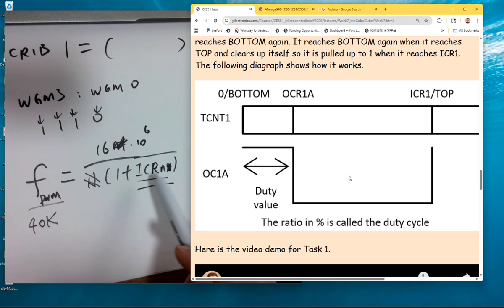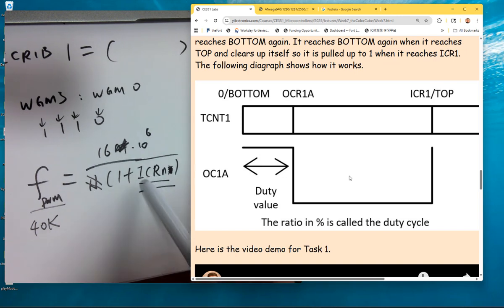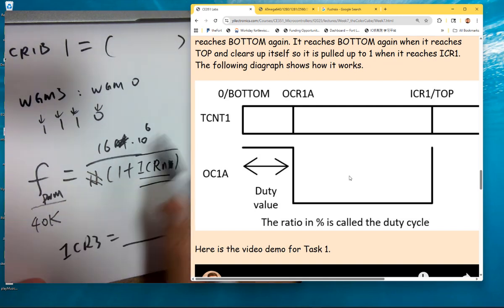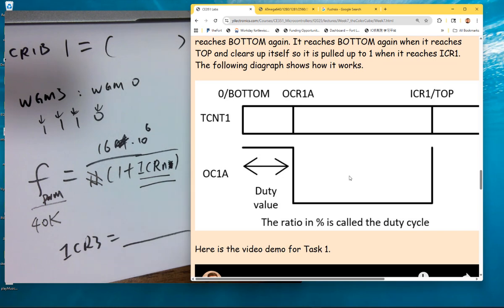So that's the register you want to assign to. And if you're looking at the problem, it's module 3, it's timer 3. So eventually, this is ICR3, right? That's the register, ICR3. You need to give that value to that register. So the name of the register in the code should be just directly ICR3. So you need this line over there, ICR3 equals whatever you calculated over here, right? And then you set up all the other registers. And make sure you are doing it with the B module.